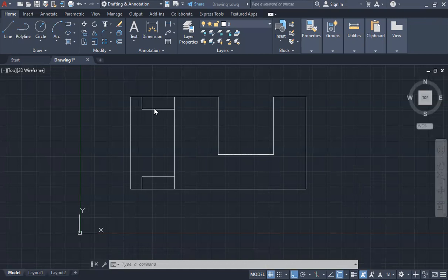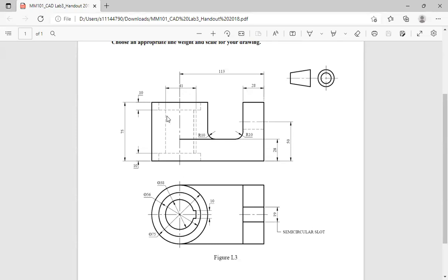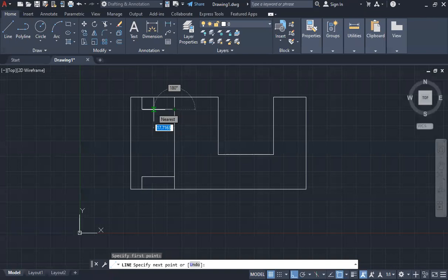Now I'll do a similar thing for this long hidden line that's in our drawing. So from the center point to that line, what would the distance be? 19. Half of 38, 19. So similar to how we did the 2 squares above, I draw a short line from this point across 19 and then connect it down to my base down here.